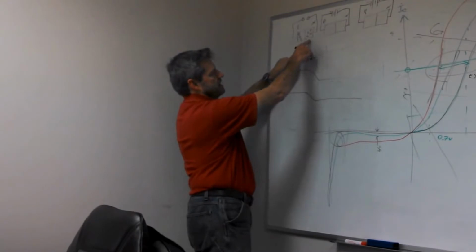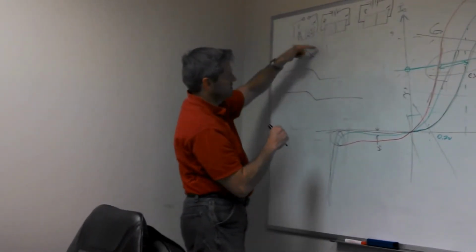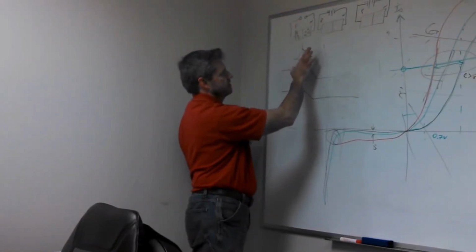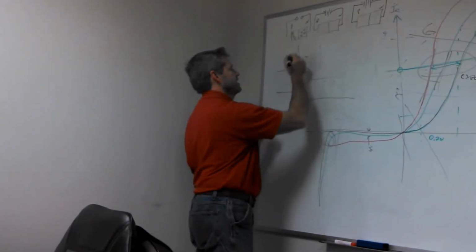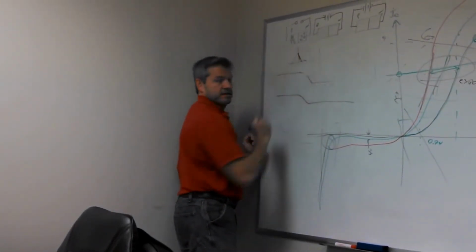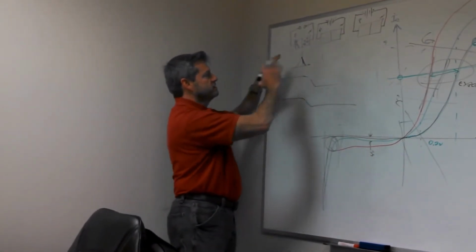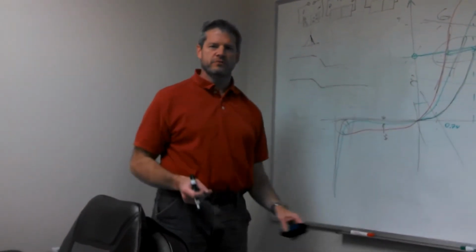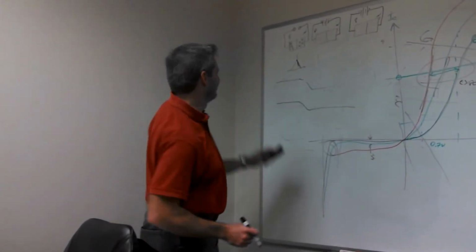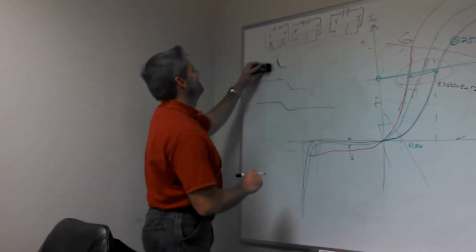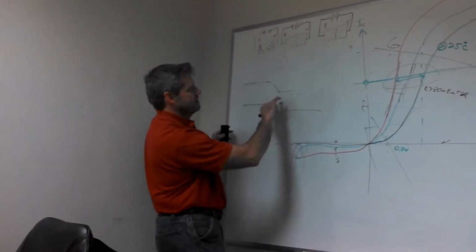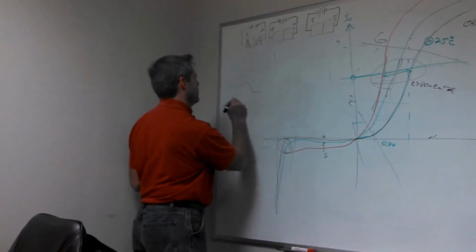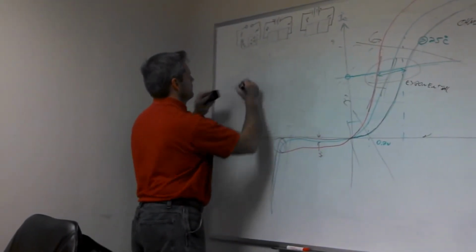But there's going to be fewer electrons that are going to be able to jump that gap over to the other side. But if I've got, say, a more highly doped P side than an N side, then I could have something that ends up looking like this, right? But in the end, this will be in equilibrium. If it didn't, it would generate electricity on its own, and we'd be rich. Figure out how to do that, we'll be rich. So what's going on here is this band gap falls like this. Well, maybe not that steep. Like this.